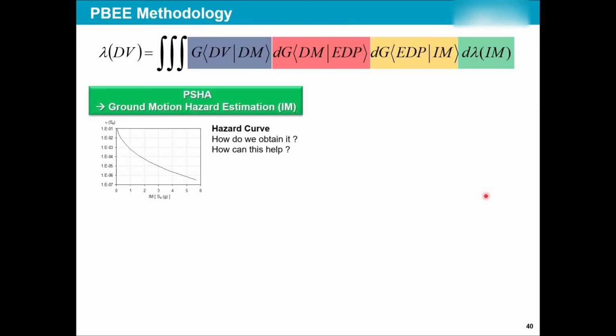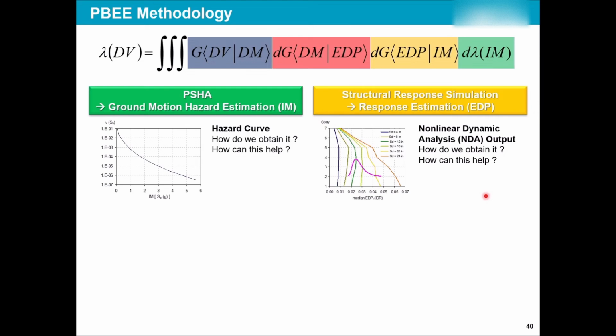So again, in simple terms, we started with a PSHA, and we got the hazard of the location. From this, we got the intensities, we got the earthquakes, which are good representatives of that area where we want, for example, our building or city to be built. Out of those, we started analyzing our building according to what we have already designed. The analysis is based on nonlinear dynamic analysis, so we are considering the plasticity, permanent deformation, the nonlinear behavior of our structure, as realistic as possible, instead of using behavior factor and design